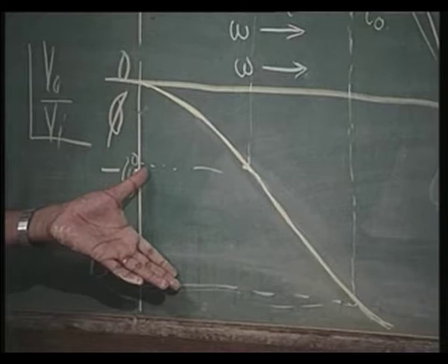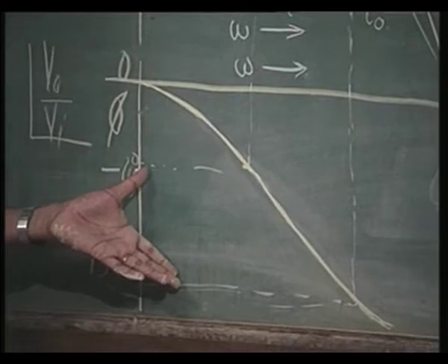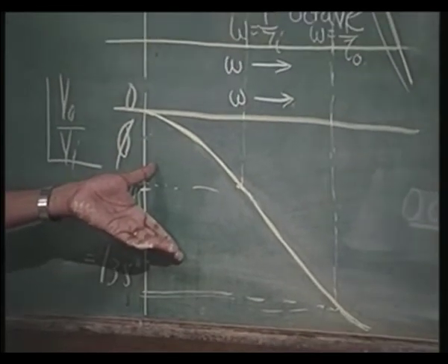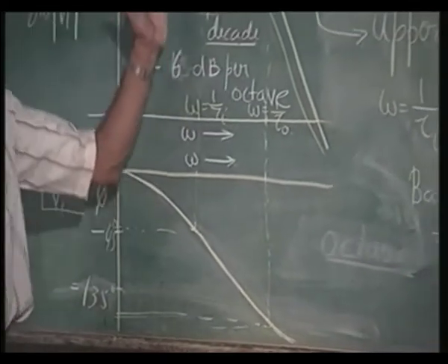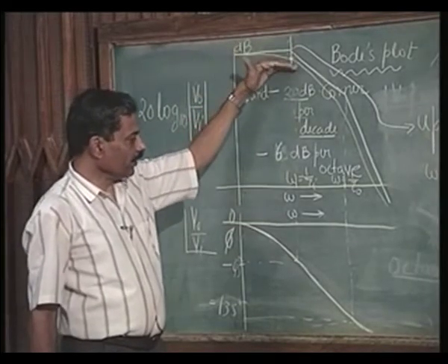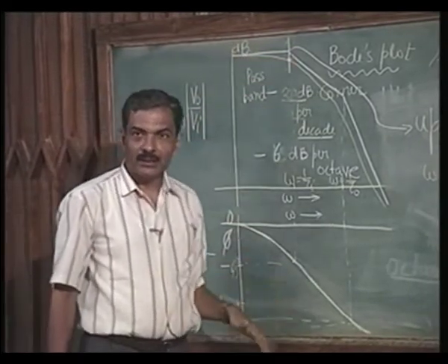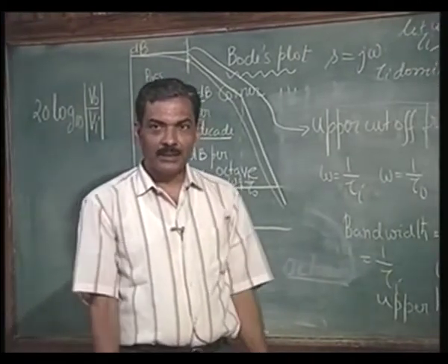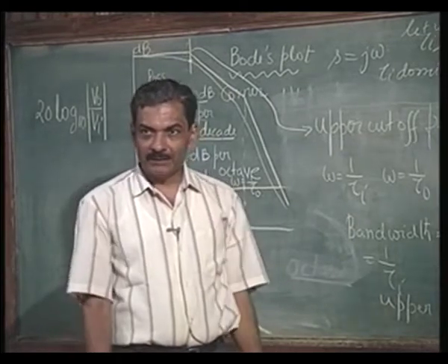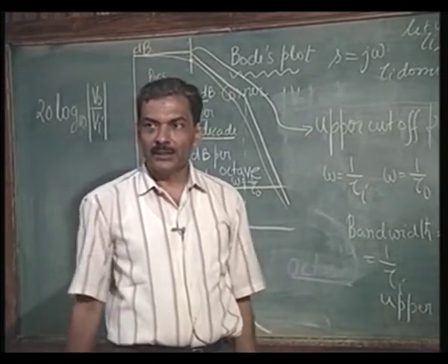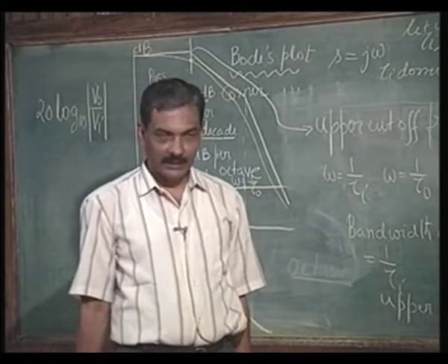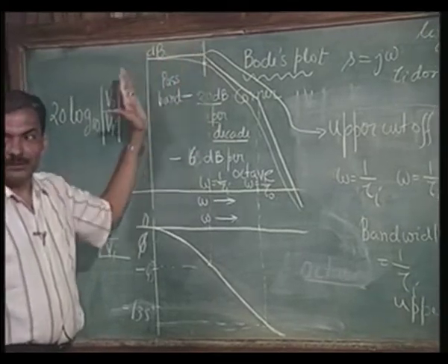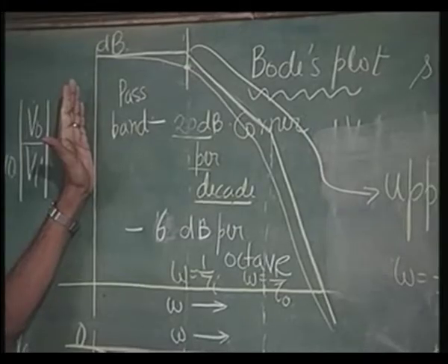Together these plots are called Bode's plot. These are important in characterizing amplifier very well. So, both these distortions, the magnitude distortion as well as the phase distortion, together contribute to the distortion in signal. Different frequency components get subjected to different phase shifts and therefore, there is a distortion in the signal. Therefore, it is required that we restrict our field of operation within the pass band.